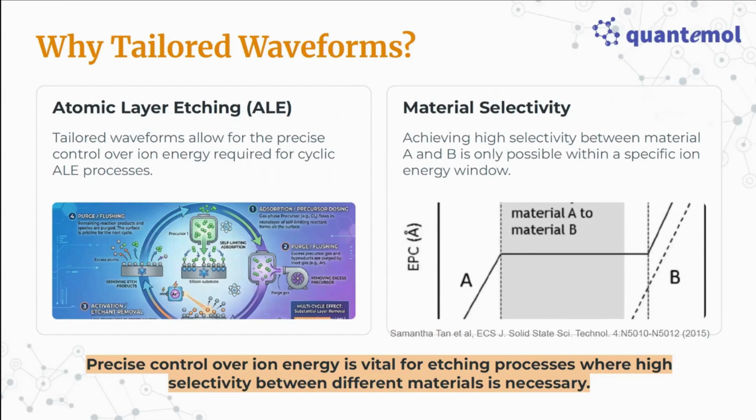So thanks for that. But maybe just to reiterate, in the end, what you want to do with atomic layer etching is you want to etch a material one monolayer at a time. How do you do this? You put in some gas, usually called precursor, which modifies the upper layer of your surface, usually with the goal to lower the bonding energy. You purge it, then you put in a plasma, and you have ions on the surface, which then should only remove this upper layer, but not the underlying material. Then you repeat this. So this really gives you an etching of one monolayer in each cycle.